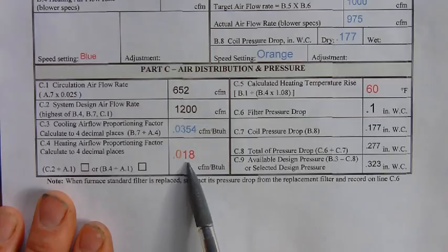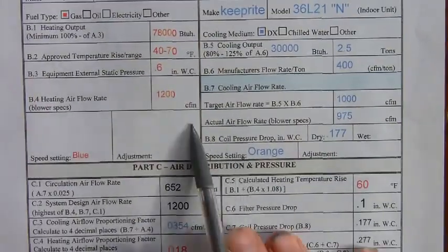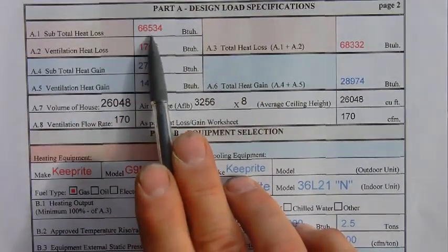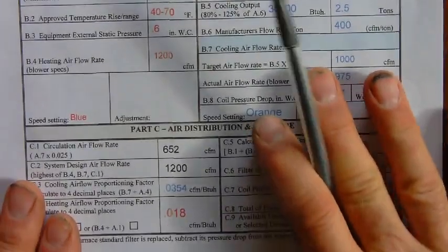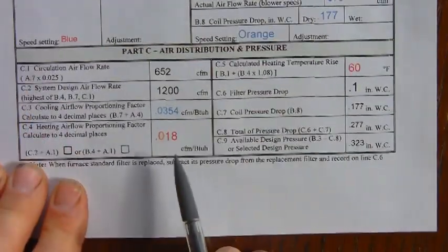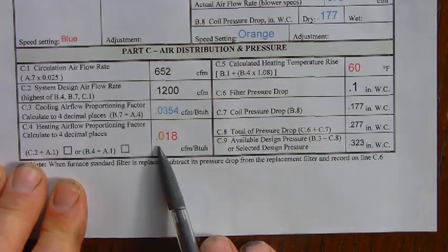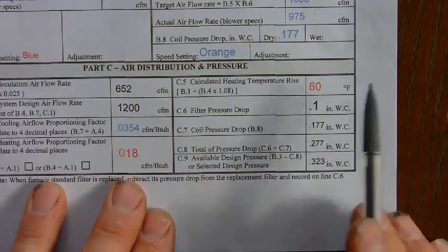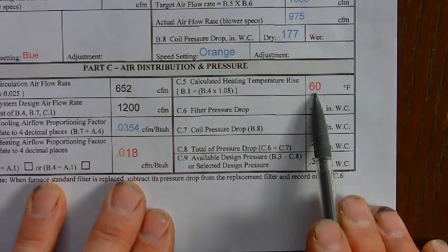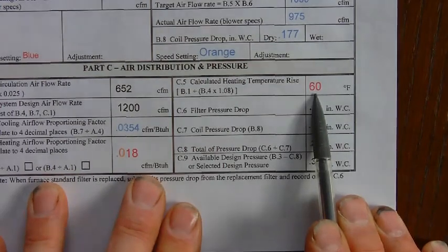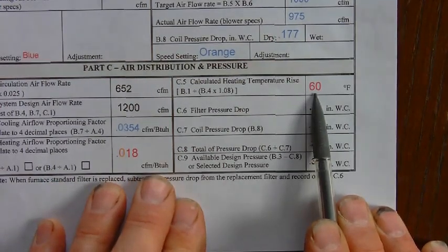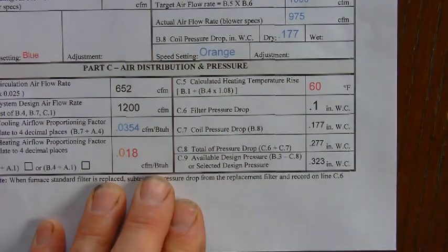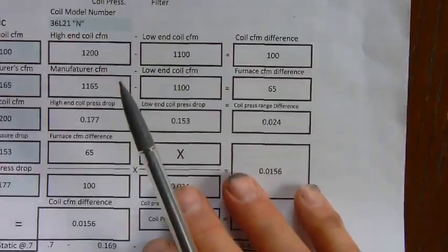For the heating proportioning factor, you're going to take 1200 CFM divided by the subtotal heat loss of 66,534, and that will give you a heating proportioning factor of 0.018. Then to verify, you've got a calculated temperature rise of 60 degrees, which is very nicely situated within the range of 40 to 70. Our filter pressure drop is 0.1, determined from your equipment